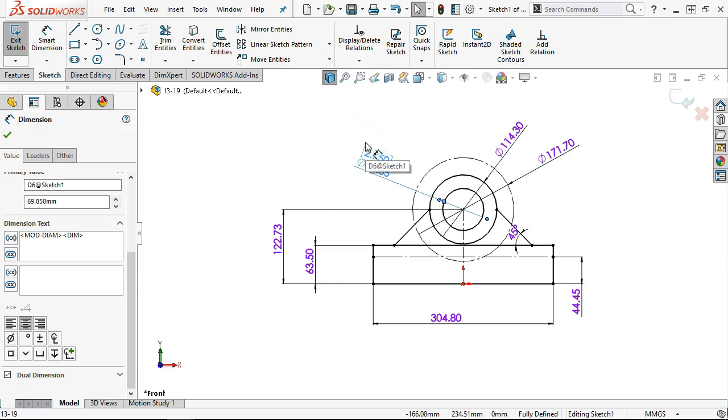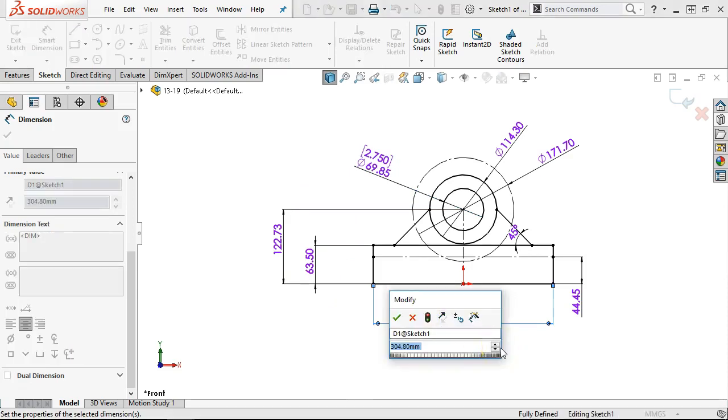And everybody knows the difference between pipe and tube. Pipe is held to tolerance on the ID. Tube is held to tolerance on the OD. So that 2.75 ought to be pretty close. Basically, the pipe, as far as steam and transmission of fluids, is to stay consistent volumetrically on the flow. Anyway, I digress. Things like the 304, I don't know that I care.